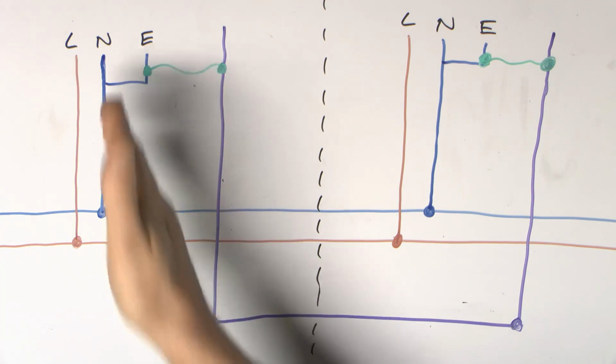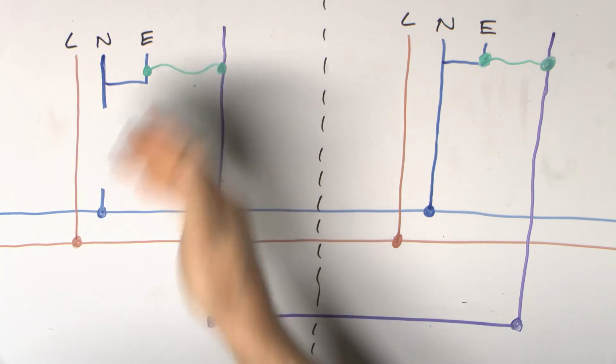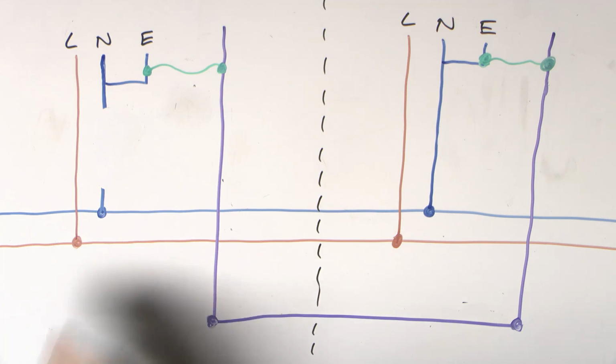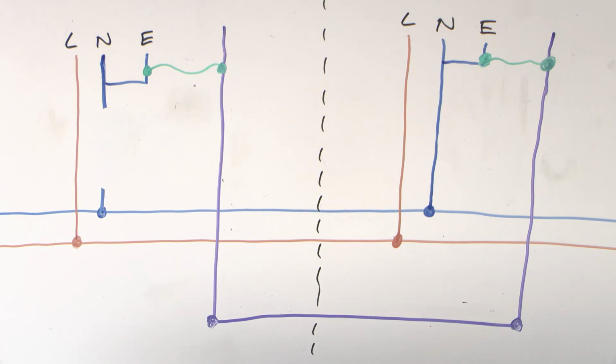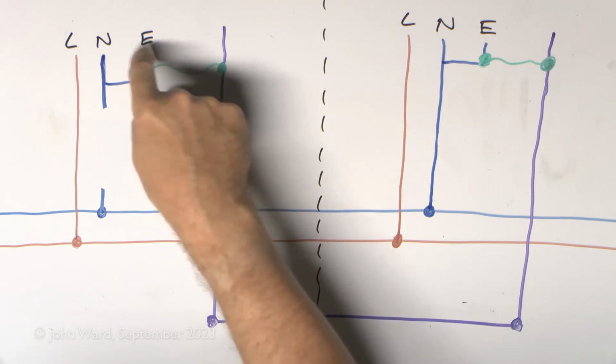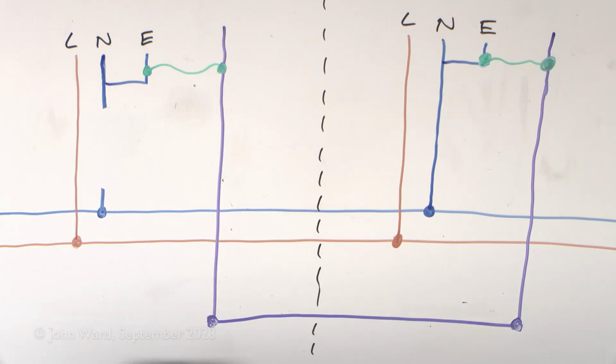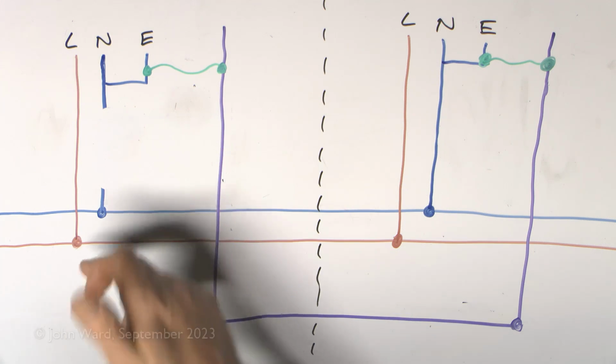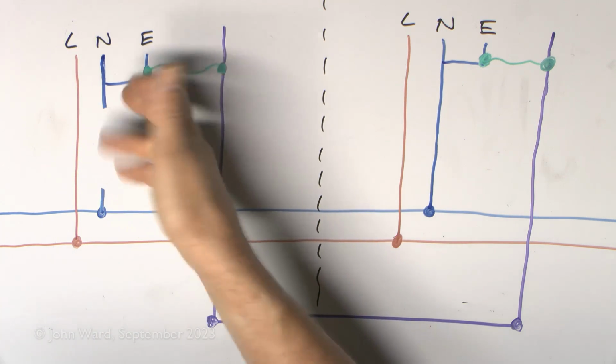Now previously, when that connection was broken, everything in the installation simply stopped working because of course there was no path for the current to flow through. The circuit's broken, so of course nothing works. And we also saw that this part here, the earth terminal and the neutral, basically goes up to around 230 volts because it's basically the end of a circuit just open there.